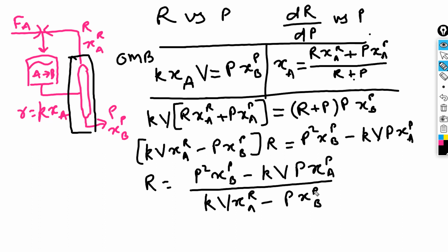And what I would like to point out to you is that, imagine that the recycle rate is increasing, recycle rate is tending to infinity. If the recycle rate tends to infinity, then the composition of the reactor effluent will be the same as the recycle composition, because you add a little bit of A and a little bit of it reacts, doesn't really matter.